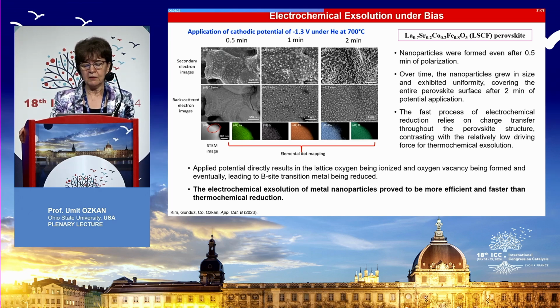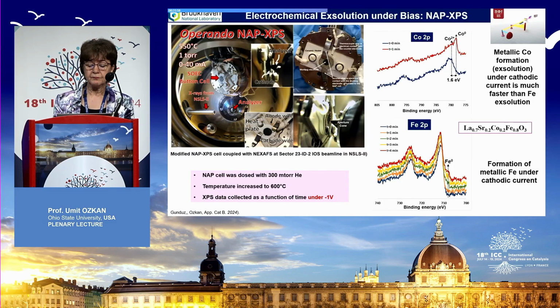In this case, again, we're looking at lanthanum strontium cobalt ferrite, and within 2 minutes, the surface is fully decorated, and you can actually see here the metal particle, and if you look at the cobalt, it's a little harder to see, but there is some X-ray mapping showing the cobalt on the exsolved particle.